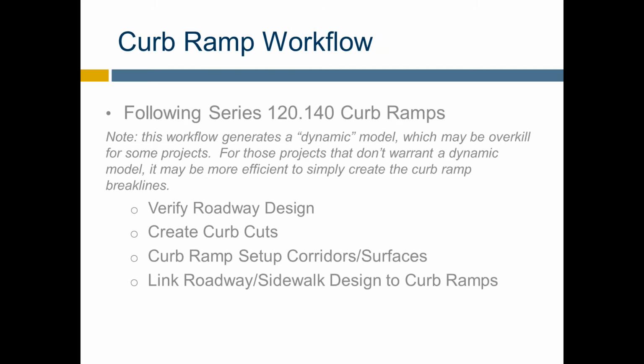So, the curb ramp workflow. The workflow that I'm following is, again, in the training manual, series 120.140. This workflow generates a dynamic model, which may be a bit overkill for some projects. For those projects that don't warrant a dynamic model, it's probably more efficient to simply use break lines, feature lines, things like that.